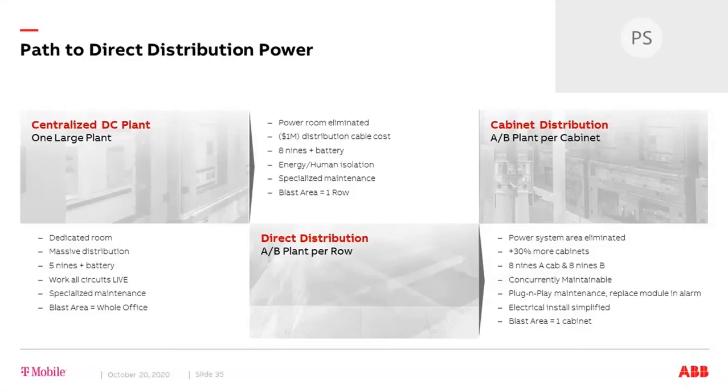If you start at the left, we phased this in over a period of 10 years, making our proof cases over time. Everyone in telecom started with a single bulk DC power plant, and many in data centers started with a single bulk UPS system with the utility bypass. From an architecture perspective, they're similar. Everyone worked really hard to ensure these bulk systems were extremely reliable. That was important because a single failure could get us on the news. Failure did still occur until much better redundancy designs were used.